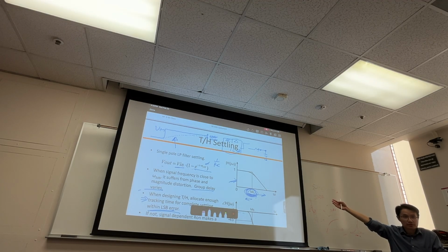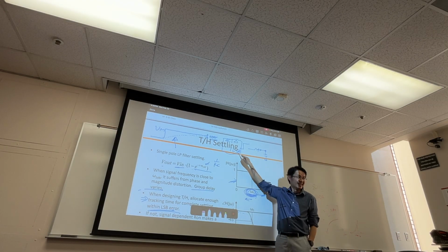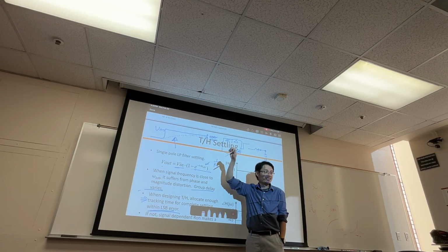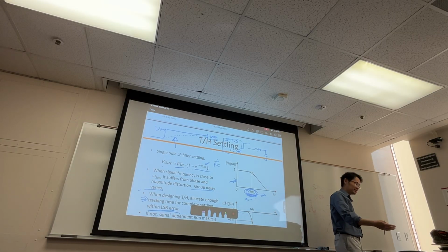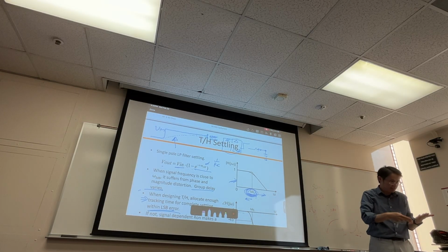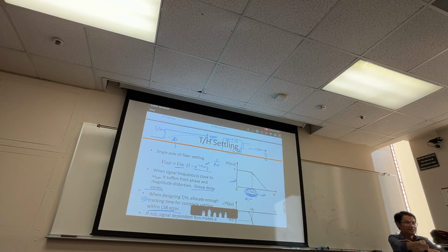Likewise, I also said that if somebody designs one more bit, you should also bow to them 60 degrees more. Why is that? In light of this, if somebody designs one more bit, why should we respect that person even more? Because your LSB is lower. That means your error tolerance is also lower. You just have to design more accurate circuits, right? So this is what I said. This is actually no joke. Design one more bit, your speed is faster. You just need to really pay your respect to that person.